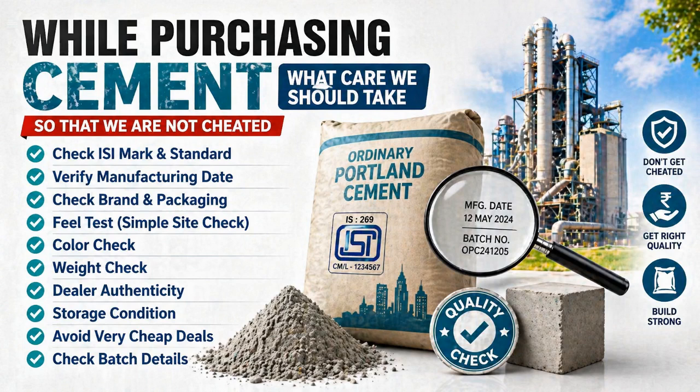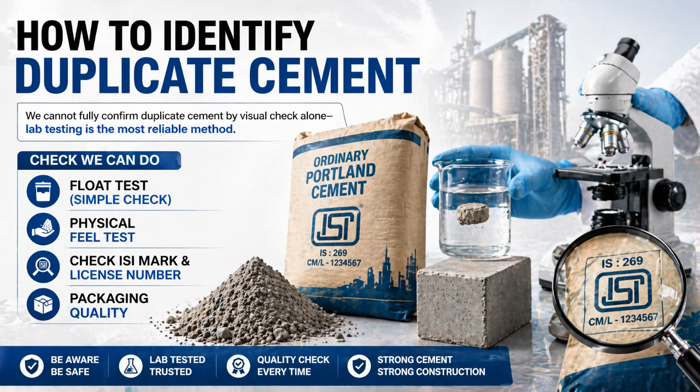Also ensure the cement is stored properly on a raised platform and protected from moisture, not placed directly on the ground or exposed to a watery surface or any moisture. Avoid unusually cheap deals as they often indicate duplicate or expired cement, and finally check batch details such as batch number, plant name and grade clearly printed on the bag for traceability.